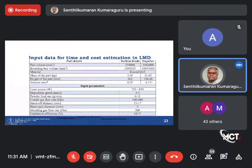So this is the good case for feature-based near-net shape. You can make a conclusion, but still we have to further study their cost models and time models, and then we'll make a decision. And we assume these process parameters for this LMD process. The power of the laser is around 750 to 850 watts, and the speed of deposition is 3 to 5 mm per second. And the powder feed is typically 6 to 12 grams per minute.